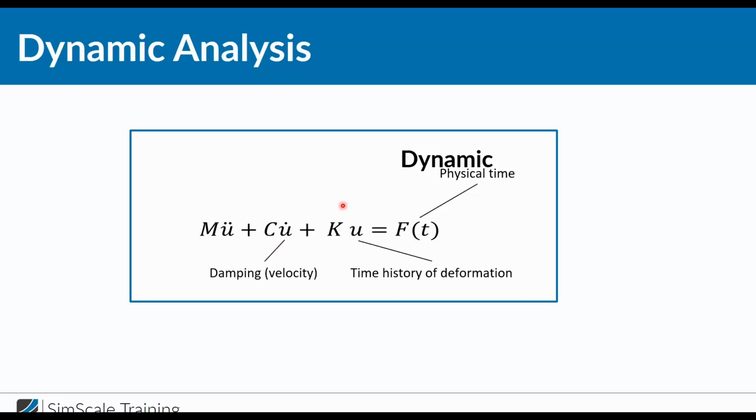And here you can see, U point is the derivative of U. The derivative of displacement is velocity, and C is the damping. In a larger model, a 3D FEA model, this is represented by a damping matrix. And finally, we also include inertial forces, the inertial component, which you know as acceleration.